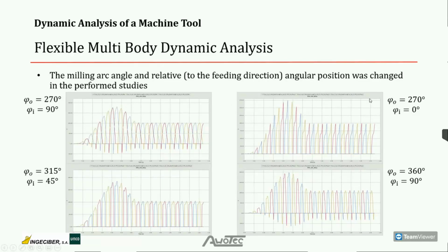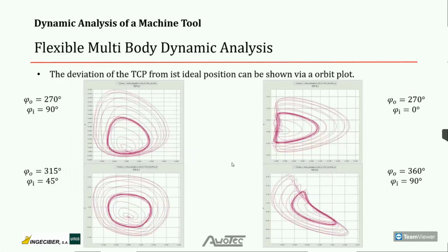But when one reduces the angles, and moves the milling arc relative to the feeding direction, it can be seen that the acting force is absolutely non-harmonic anymore. And from these functions you can estimate that different dynamic effects will result out of this.